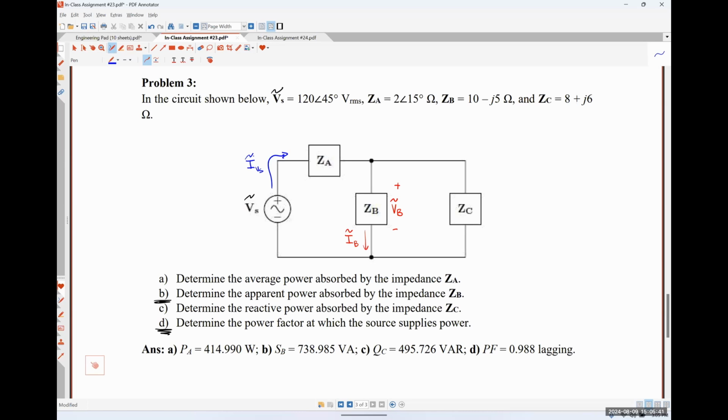Voltage division. So voltage division, to me, is the easiest way to get that information. If, for whatever reason, you were so inclined to try to find the current, though, you could do a source transformation on this guy and then use current division to find IB first. Not saying we have to do that by any stretch of the imagination because it is technically two steps where we can get the voltage in one, but that is definitely a way that I've seen students approach this one, so I just wanted to mention it.